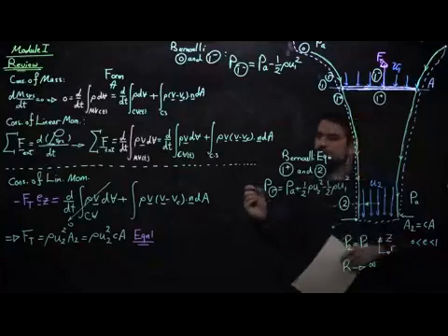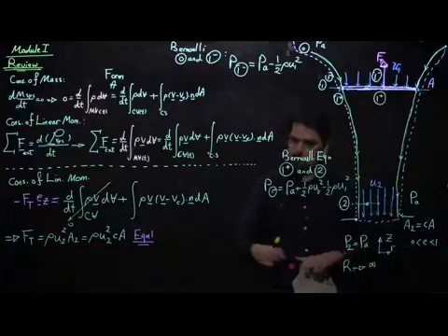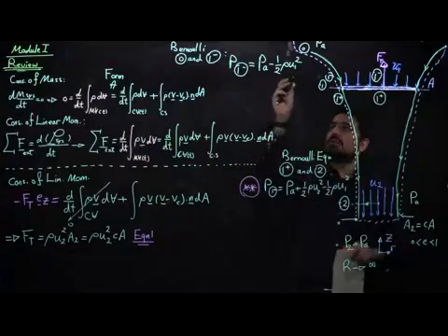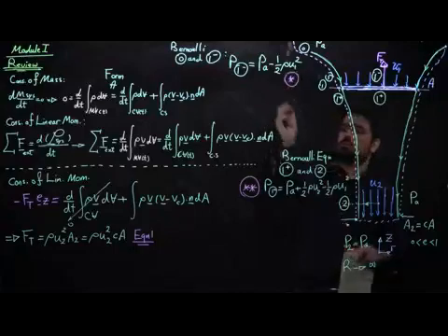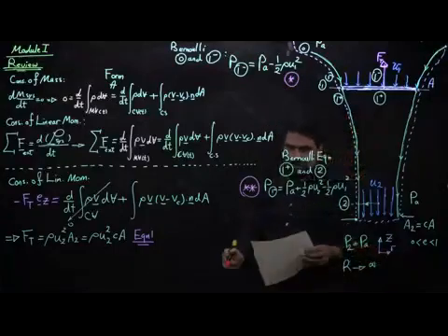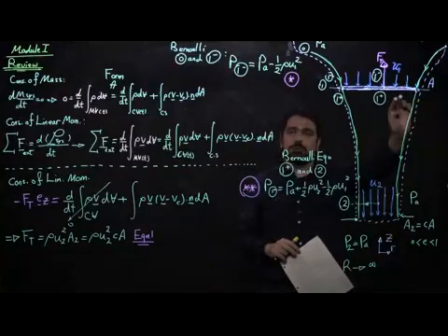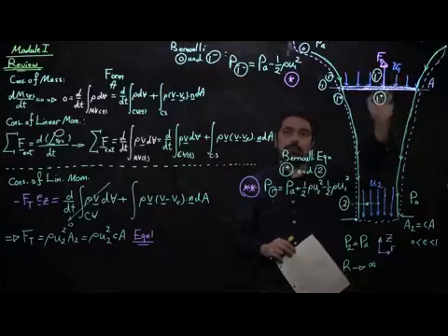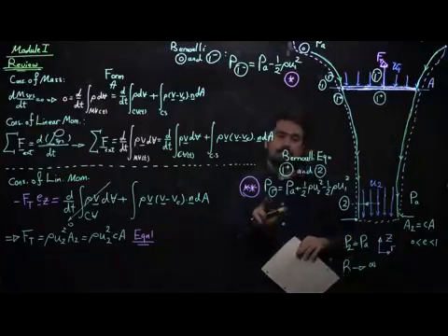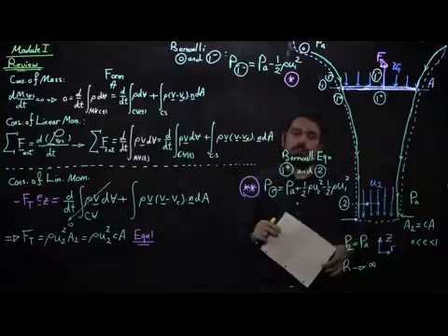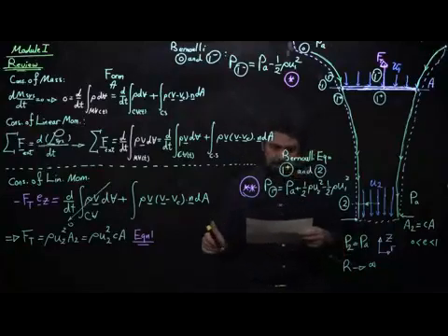So I have one expression that describes pressure based on Bernoulli at position 1 plus, and I have another expression that describes pressure at point 1 minus. And now I can think of what these two pressures really do for me. One is the pressure right beneath the blade, the other is the pressure right above the blade. It looks as if P1 plus is higher than P1 minus. And there is indeed a difference.